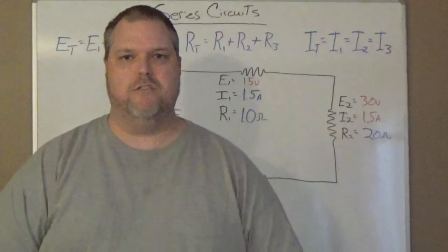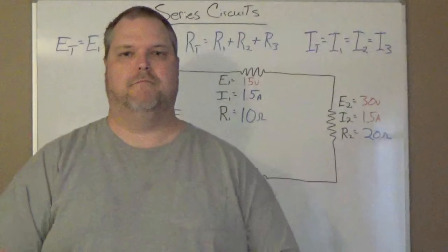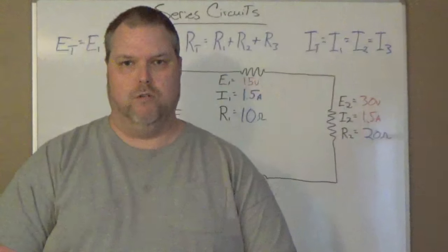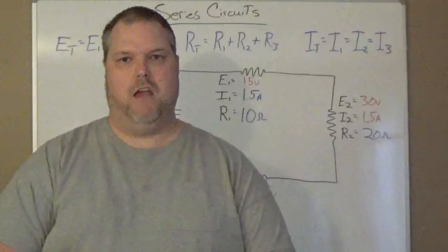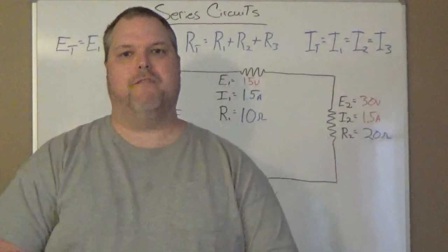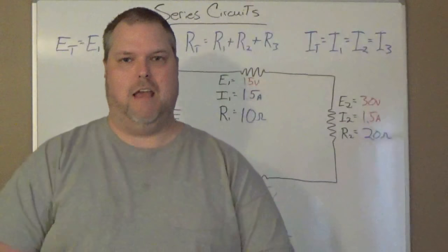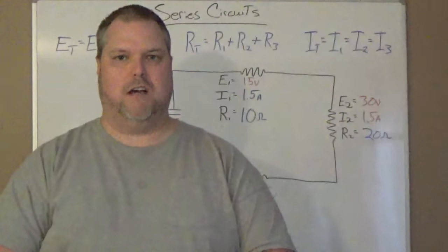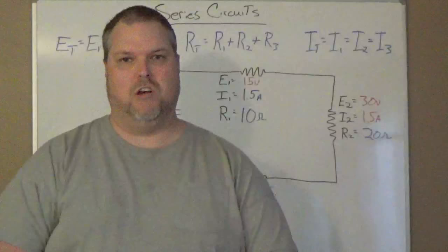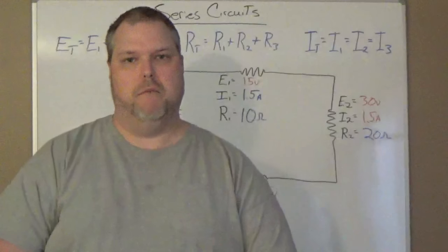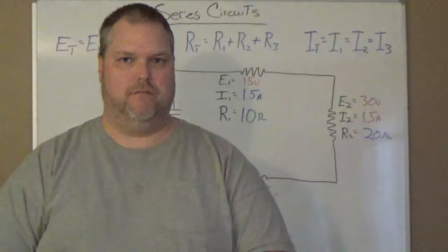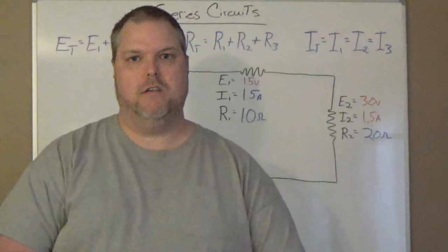The more resistors, the more math. But the basic things that you're going to be looking for is volts, amps, and resistance. And you have to remember that volts and amps and resistance are going to be found in all types of electrical. When solving a series circuit, remember, volts is additive, resistance is additive, amps stay the same.